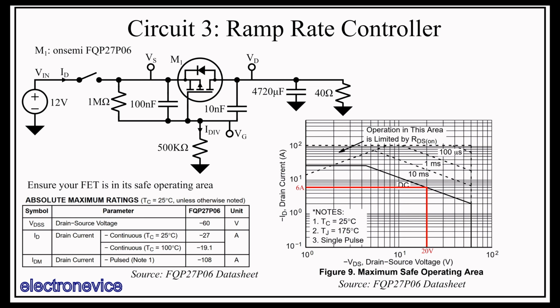One would think minimizing this gate source capacitance would be best to minimize this error. However, there are two other more important effects. First, the gate source capacitance along with the gate drain capacitance increases the amount of time from the turn-on of the V-in voltage and the plateau due to the time required to charge up this capacitance. And so if you need a longer delay, you can increase this capacitance a little at the expense of increasing the Miller plateau flatness error. However, more importantly, this gate source capacitance forms a capacitive divider with the gate drain capacitance that determines the gate voltage right after power is applied.